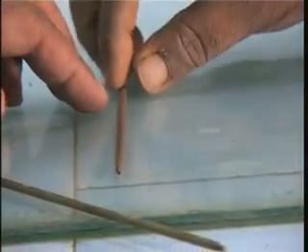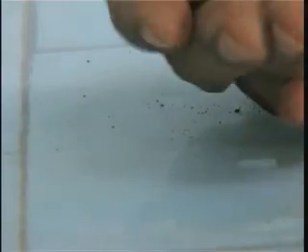And you can see that this could be actually rolled to 3 millimeter size, and the sample didn't crack. So we need to have a little bit of drier sample, and if it is slightly drier than that one, then we won't be able to roll a thread of 3 millimeter size. You will see that in the next little bit.